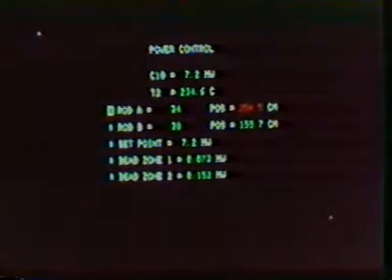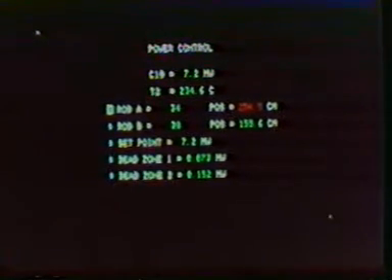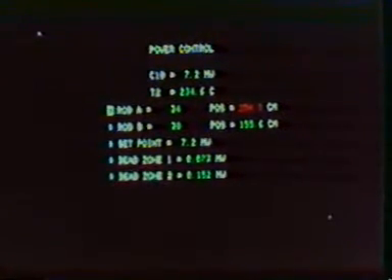By means of a control program, the reactor power is adjusted and kept at set point. The operator can easily change control parameters such as the power set point, the controller deadband, and the control rods used for the control.